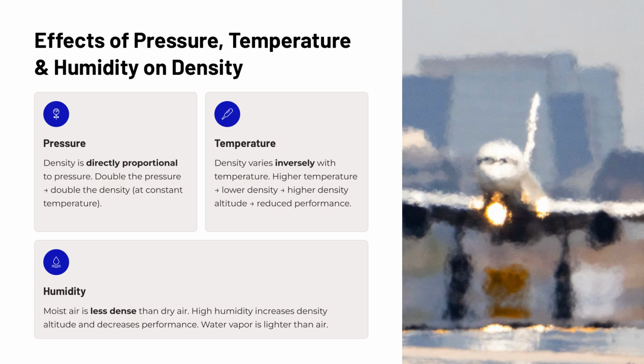Humidity is often overlooked, but it matters. Moist air is actually less dense than dry air. This surprises many people, but water vapor is lighter than the nitrogen and oxygen molecules it displaces in the atmosphere. So on a hot, humid day, you're dealing with the combined effects of high temperature and high moisture content, both working against you to increase density altitude and degrade aircraft performance. Never underestimate the impact of humidity, especially during summer operations.